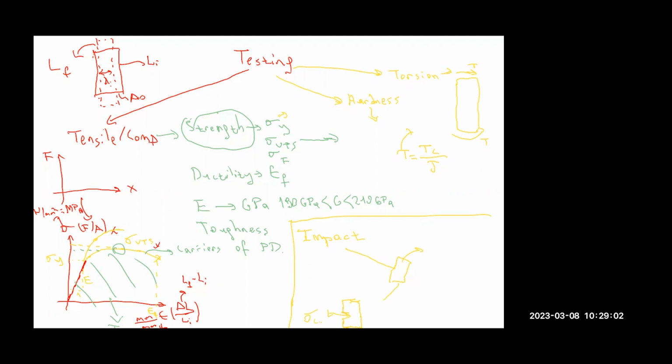Then we hit the sample and we observe the amount of energy that the sample absorbs, and we monitor the impact energy versus temperature curve.